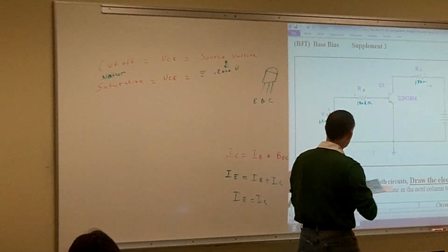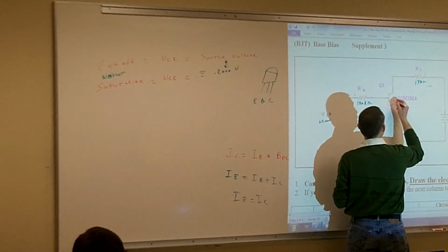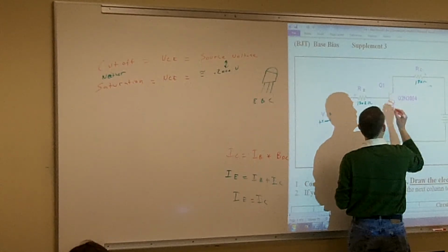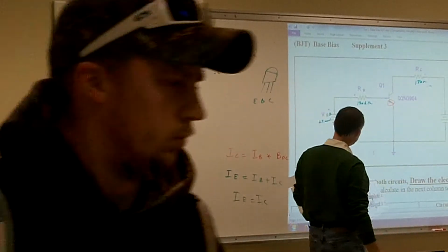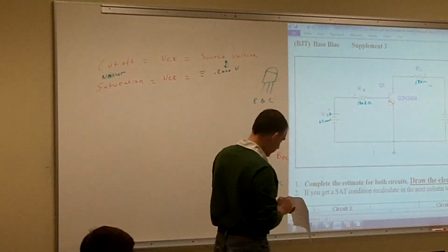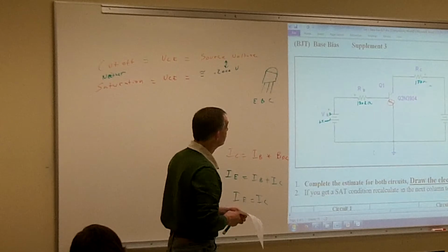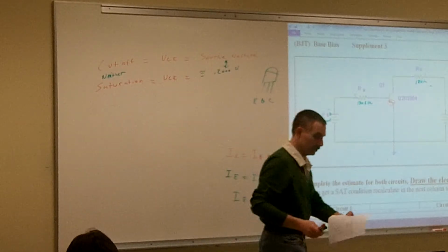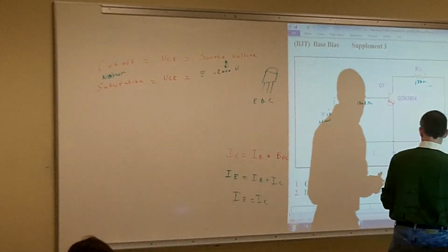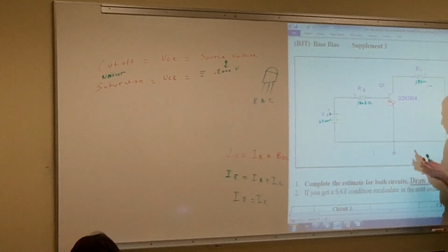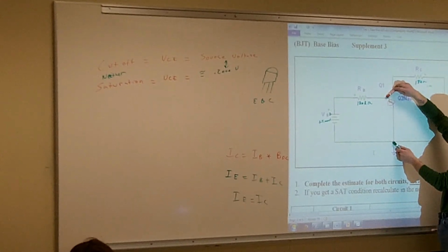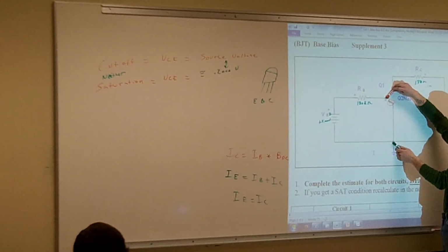Yeah, circle the active component, and then inside your circle put the polarities of your active component, the negative, positive. Then what's my next step? Yeah, test voltages. So treat that base to emitter as if it was an open. And what would I measure for voltage at this point here?